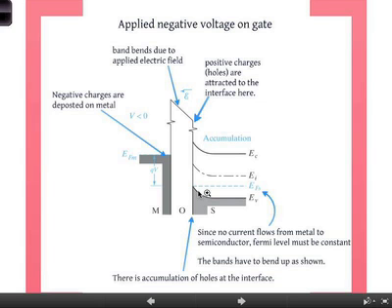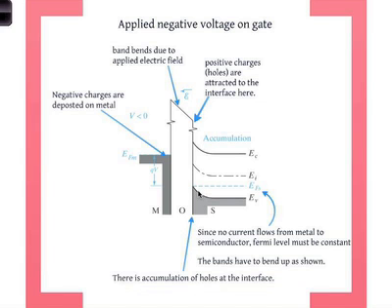Now, what is the situation? This is the situation we didn't actually talk about because it's a negative voltage on the gate. It's the opposite of cutoff. Okay? So remember, this diagram is rotated 90 degrees to get that. Okay? In that situation, what we have is basically lots of holes here in the channel. Okay? Which means that if you apply voltage, of course current will flow, but the gate has no control essentially.